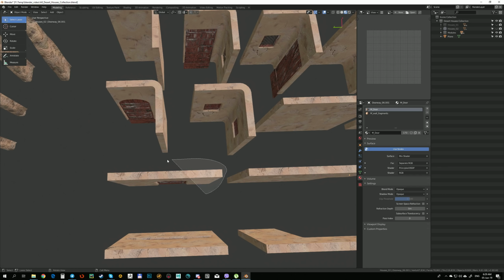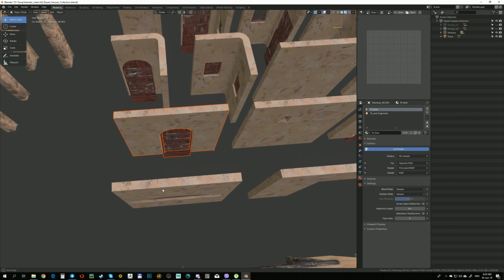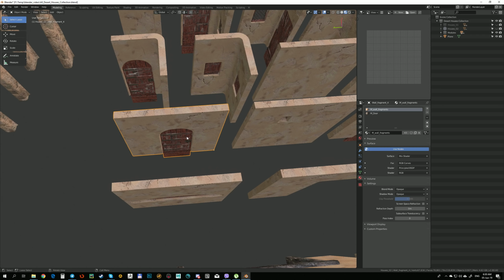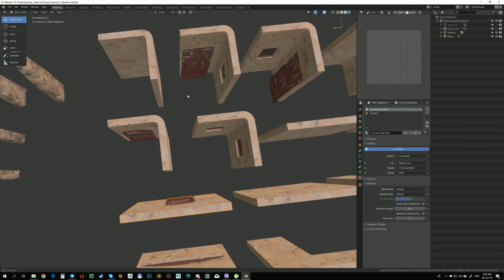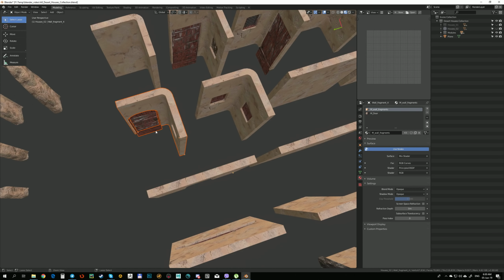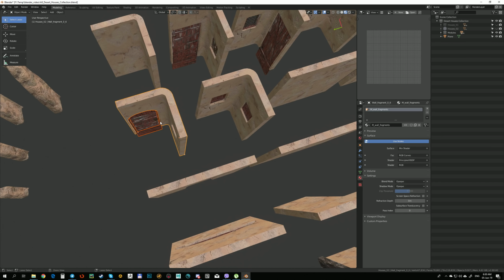If I use my tablet to select the element, then Shift left click on one of the elements to make the outline brighter, then Ctrl J to combine elements. If the outline is not brighter, and I hit Ctrl J, nothing happens, so I need to Shift click on one of the elements and hit Ctrl J.